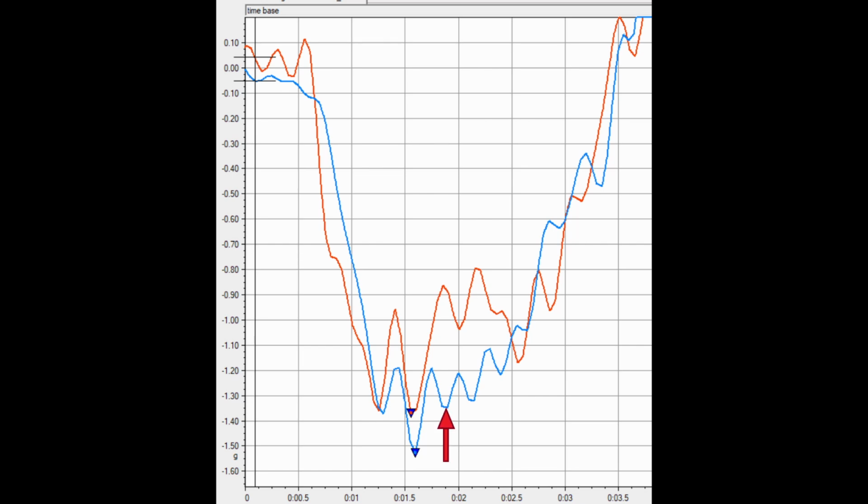You can see it has a higher overall lateral acceleration compared to the line in red, which has a higher angle, increased jacking force. You can see the red line, which is a car with higher angle, more jacking force. The lateral acceleration is wider on both sides of the turn, but with a lower peak.